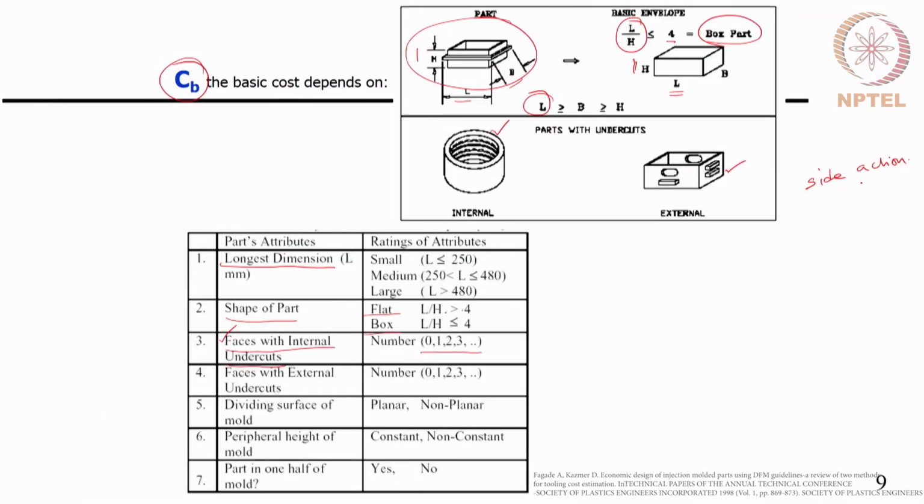Small features can be obtained because the plastic components have flexibility. So, while ejecting, maybe the part can be slightly flexed and it can be taken out of the cavity, but big features, through holes in the lateral directions, cannot be taken out. So, we need side action pins or side action mold components.